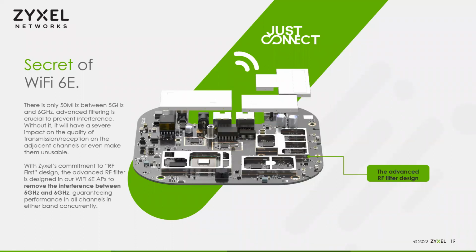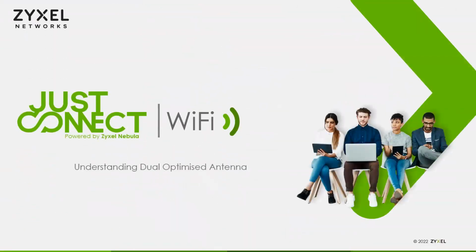So one of the things here that we just wanted to highlight has to do with the shielding. As you guys know, if you've attended some of my other wireless webinars, we're really big on shielding on our devices. That includes additional actual shields around the devices, as well as moving the antennas onto their own PCBA and putting a shield between them and the main board. The idea behind this is to help with those marginal connections, as well as any interference you may get from bleed over from 5 gigahertz devices, as well as interference from 4G and 5G devices that might be nearby.